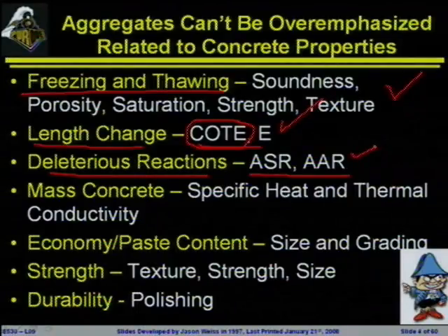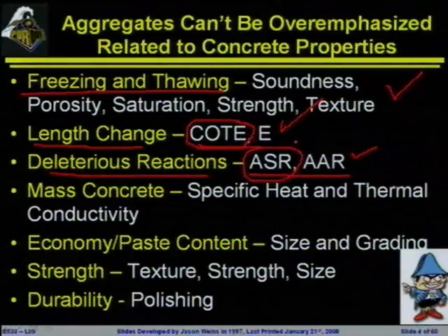And this is a big issue in quite a few structures, because once it starts a cracking process, once it starts the damage and degradation process, there's very little that can be done to retrofit or repair this. There's a lot of research going on into figuring out ways to stop ASR problems once they start, and to really go back and retroactively try to fix that concrete to prevent that reaction from occurring even more.